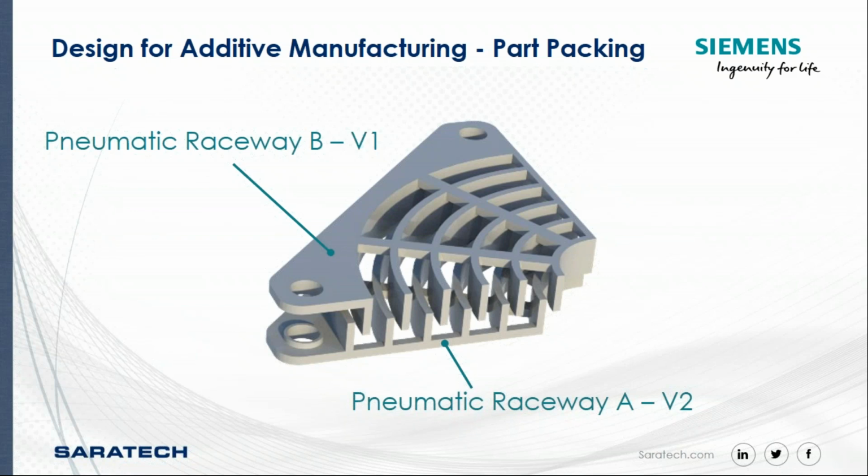It's a small design consideration, but again, something you want to do at design time with knowledge of the type of printing you're going to be doing, the machine you're going to be using, and the method you're going to use to print, taking that information and adjusting your design just slightly to make an A and a B version of a part that will pack much tighter into a build volume and give you much better efficiency than you would have with just a single part alone.